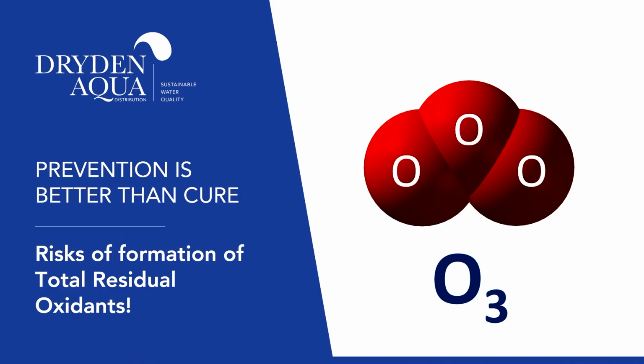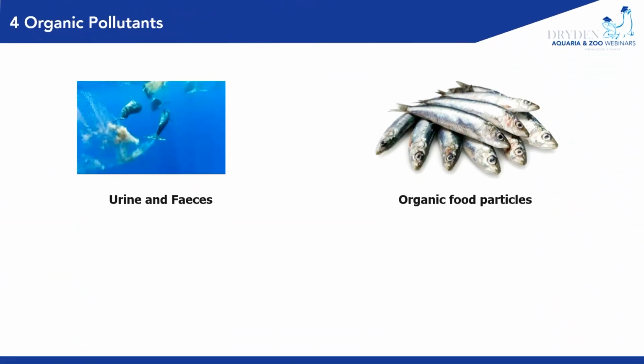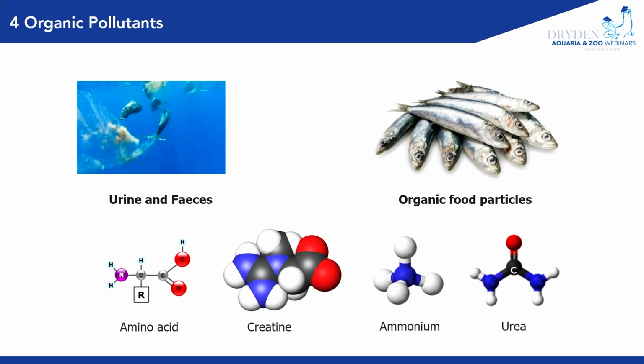And that's where we start talking about ozone and the increase in the requirement for ozone, because your ORP is reduced continuously by this metabolism of the organics in your system that's not being ejected out of the system. So your ozone consumption goes up, your ORP goes lower, and you keep trying to compensate for each other, because your urine and feces and your food input stays the same, right? But everything else is going out of balance.